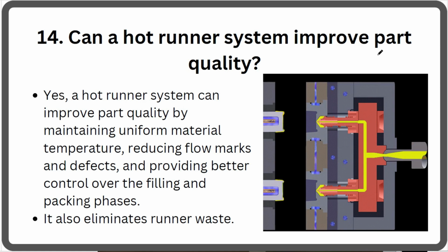Can hot runner improve the part quality? Yes, hot runner systems improve the part quality because we are keeping the material in a hot molten condition. In every cycle we are directly injecting the molten plastic into the cavity, so there will be no removal of the runners and cooling of the runners. There will be no wastage, and this hot runner system also improves the quality.